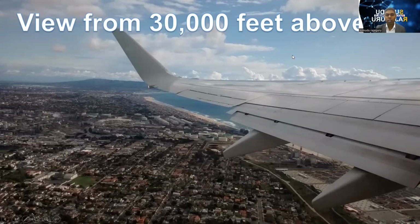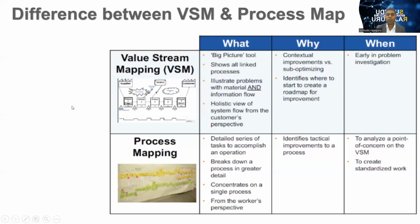So it is important to discuss a little bit the difference between process mapping and value stream map. You can see here, all things included. When we go into the value stream mapping, it is actually the big picture. All linked processes illustrate problems with material and information flow. So when we draw the value stream mapping, there are two parts we have to address. One is material flow. The second one is information flow. It is a holistic view of system flow from the customer's perspective.